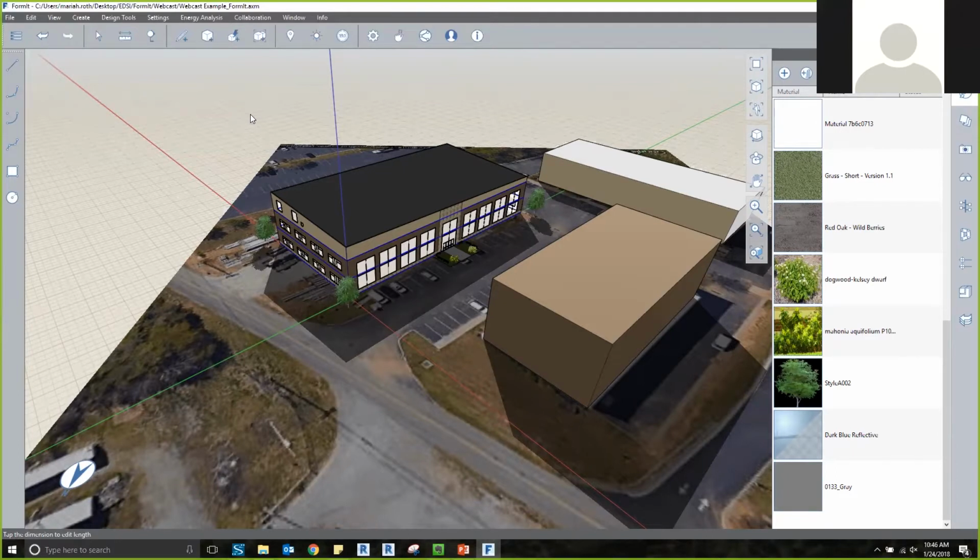And vice versa, if you were in Revit and you have a folder of Revit families, again, the ones that FormIt approves of, it cannot be a hosted type of family. You can use the add-in tool within Revit to go to that folder, and it will convert everything within that folder over to a FormIt style of family. And that's how FormIt is able to read those families from Revit.